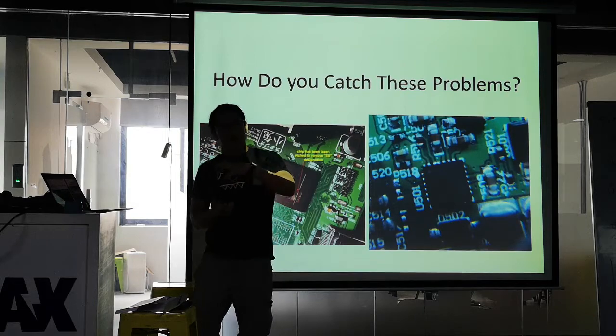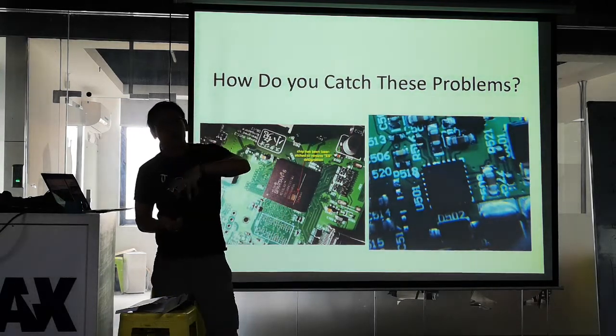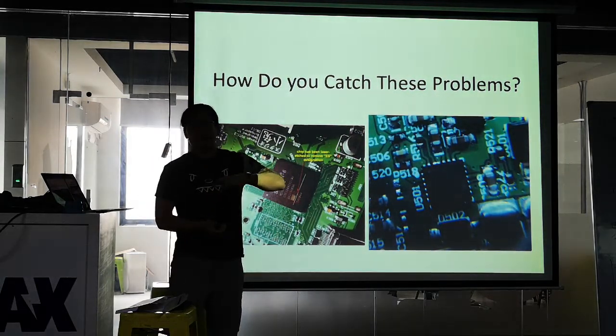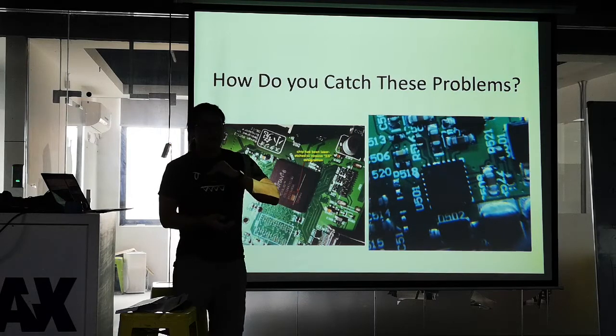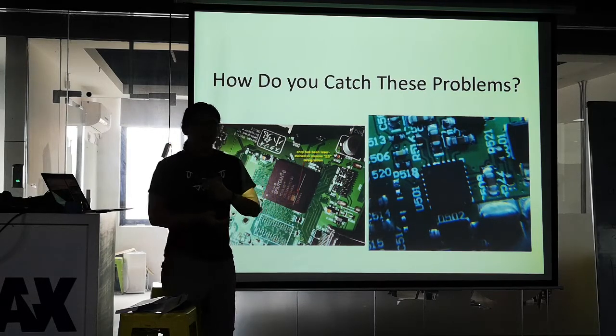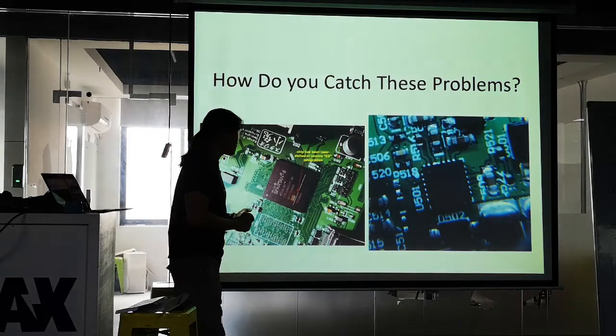With the BGAs, they tend to just sort of self-align. They're much easier to solder. Once you get the stencil right and you have the process right, they're more consistent in my experience.